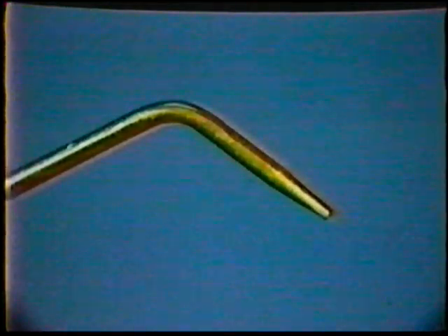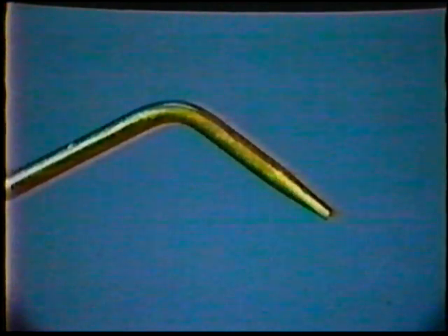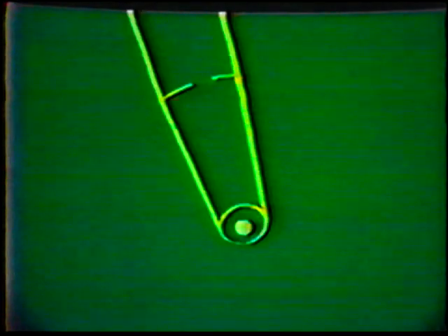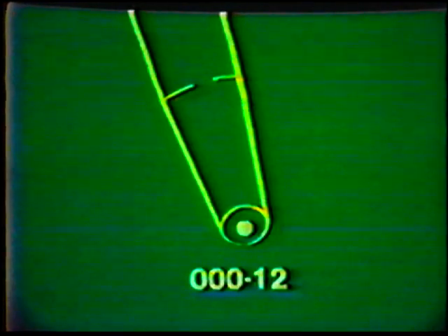The tips used with this process are usually made of heavy-walled copper for greater resistance to reflected heat. There are many types and usages. Generally, the same type of tip is used for welding, brazing, soldering, braze welding, and hard surfacing, and is angled to allow comfortable use. Tips vary in size and length based on the volume of heat needed for the work. The orifice sizes generally range from 000 up to 12, numbers which represent measurements used by various manufacturers. Cutting tips also vary in size and shape, based on the volume of oxygen needed to cut.